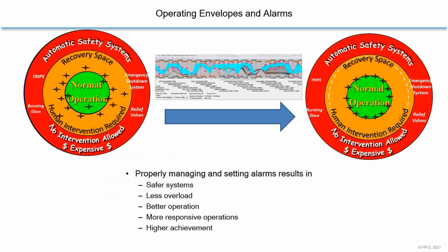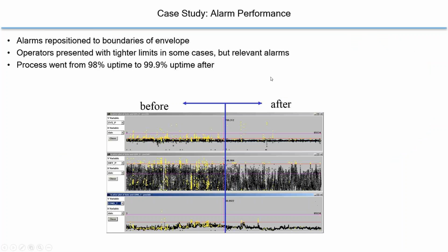Another application area is in alarm management. So one of the key ideas of operator alarms is they provide feedback to the operator when it's time to react to the process to keep it running in the area of normal operation and to avoid any of the safety systems taking it down. So the key things there are process availability, avoiding any of the safety systems interacting to improve our safety, but also improving our profitability and economics. And the key things can be seen there.